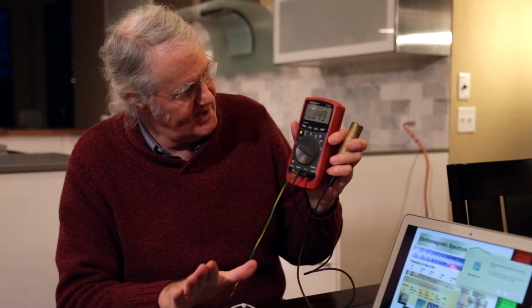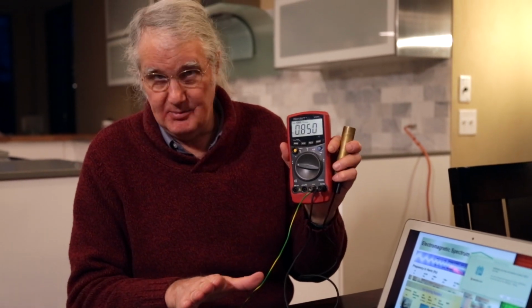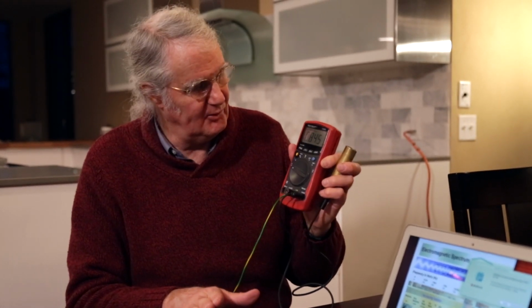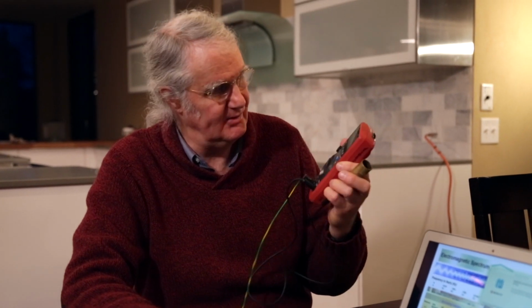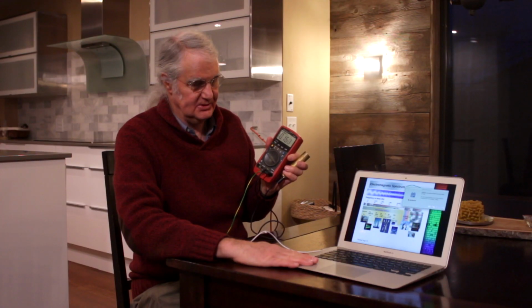And now when I have my hand close to it, it's only 800 millivolts, 0.8 volt, as opposed to 5,000 to 6,000 before. And when I touch this, it actually goes down because this is grounded. This chassis is now grounded. And now it's down around 200 or 300 millivolts, 0.2, 0.3 volts, relative to Earth. And that's a good number for daytime exposure.